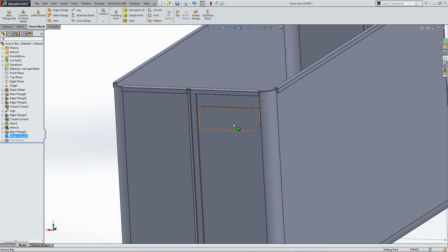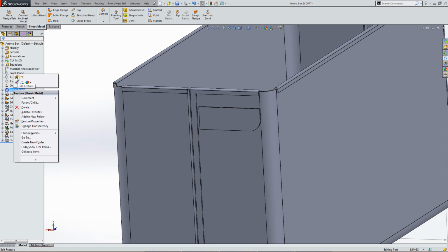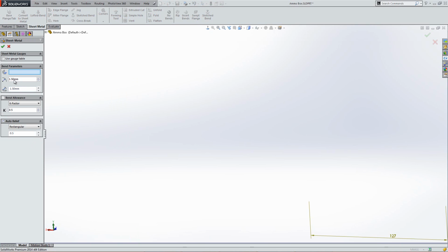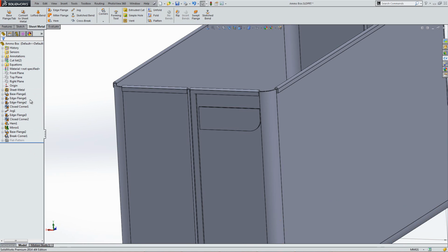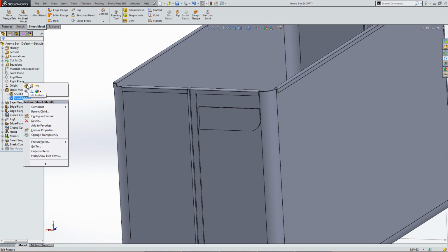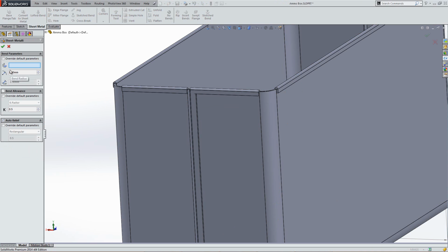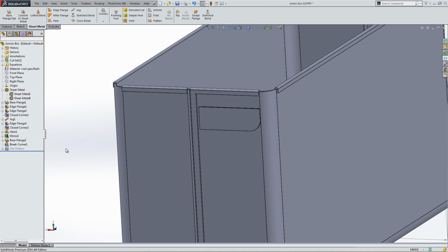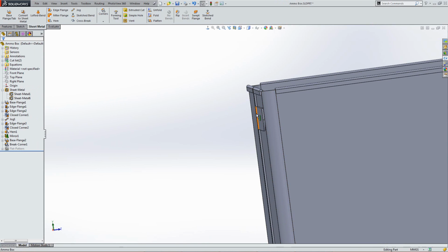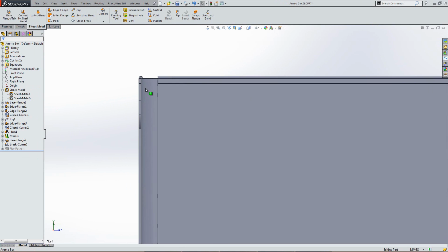So next we're going to create our hinge. What I'm going to do is just double check that our internal radius is 1.5, which is correct, and that's going to be for all multi-bodies here. Now we can go into the multi-body and edit it if we want. We can overwrite it for that multi-body, but it's right now, so we'll okay that.